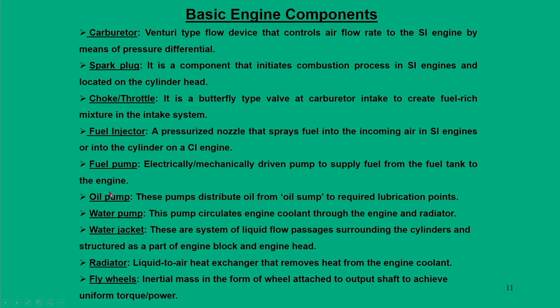For example, when the piston moves within the cylinder, there are piston rings and there is some space in which the lubricating oil also has to be pumped in, because we expect the piston movement to be smooth within the cylinders. So, for that reason we call this an oil pump, typically the lubricating oil pump. It distributes oil from the oil sump to the lubricating points.